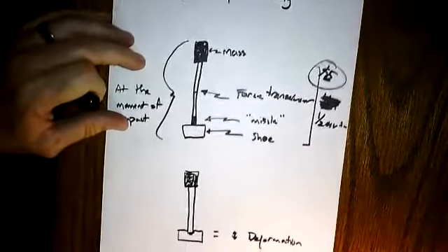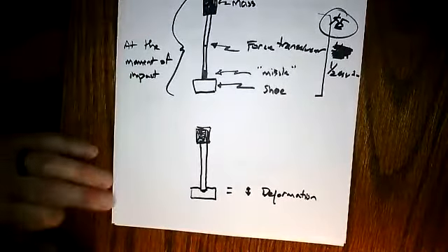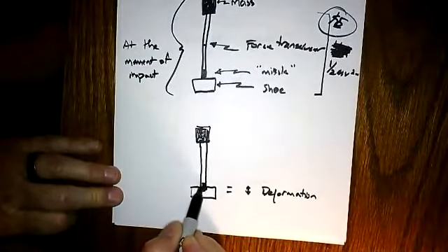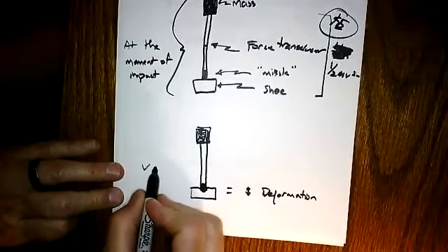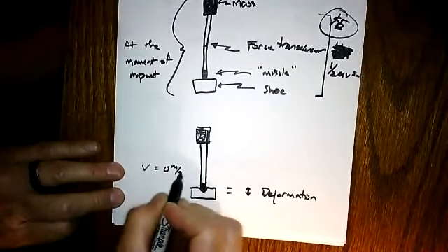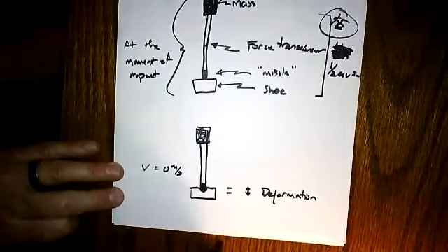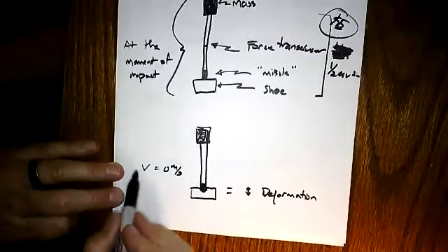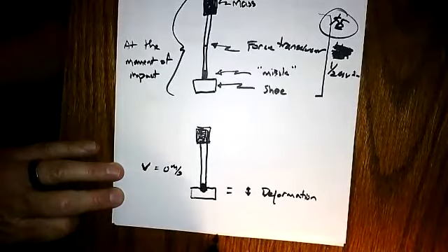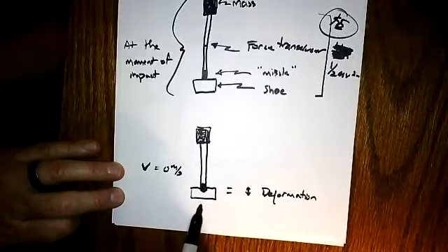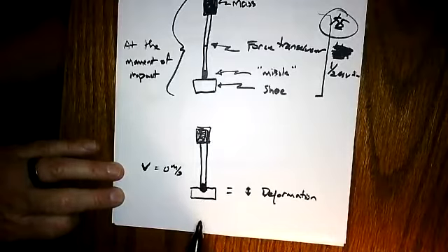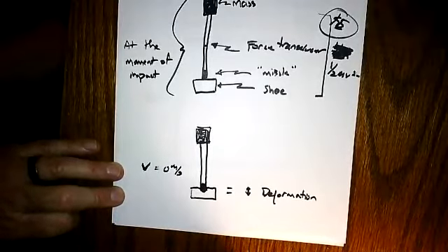So here is the moment that the missile has deformed the shoe, and the velocity at this moment in time is 0. So we have maximum deformation in the shoe, the material has been compressed, and the velocity at this moment in time would be 0. And then naturally this shoe would uncompress, and it will push back up on the missile, and the missile will be lifted upwards and ultimately re-airborne. So it will bounce on the shoe.